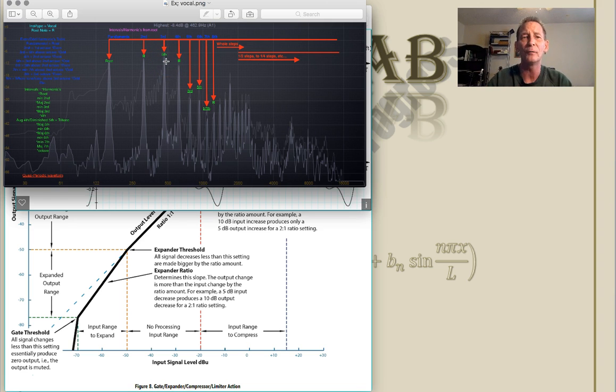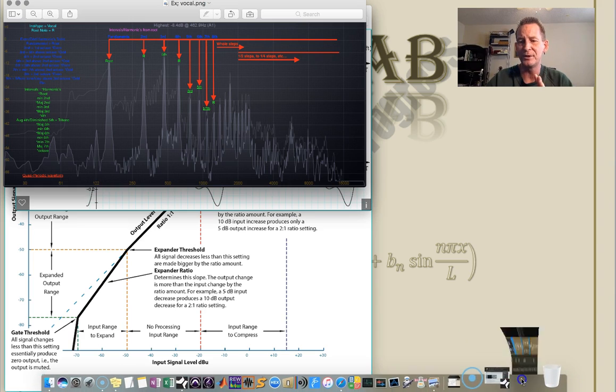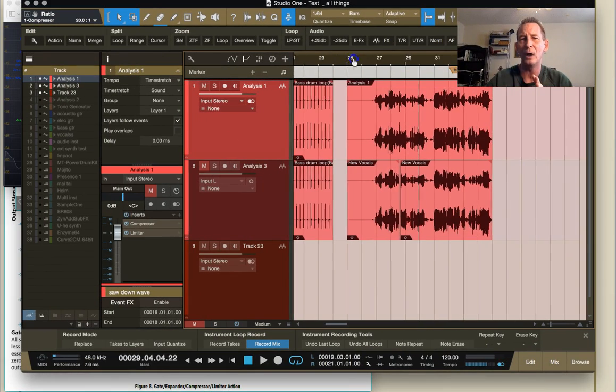So unless you're just using limiting, theoretically you're actually compressing the dynamic range. You've got to be careful that when you're compressing, it might be reducing this down 3 dB and this only down a dB and a half, and it's starting to push the dynamic range closer together. You've got to be real careful about that and keep that in mind. For the strict use, in my opinion, of using a limiter and a compressor for just reducing some dynamic range, for things in the audio that are too loud, the first use of it is real simple.